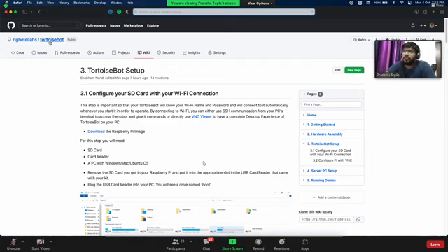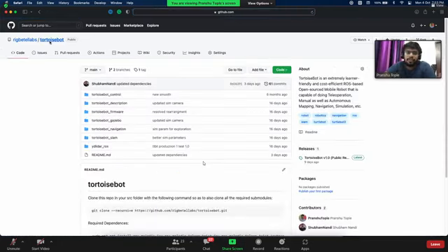In TortoiseBot itself, we are publishing odometry using a SLAM technique called Cartographer. So that provides you the odometry reading using the laser data. So either you can use a LiDAR to get odometry, or you need an encoder to get the odometry. So you have these two options: use a wheel encoder, or you can use a LiDAR. You can use both. Once you get odometry, then you can give it any coordinates as you want.